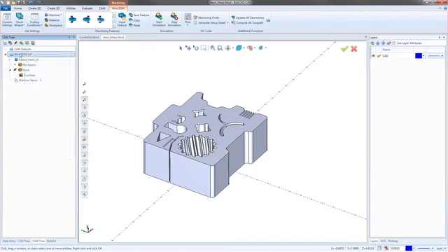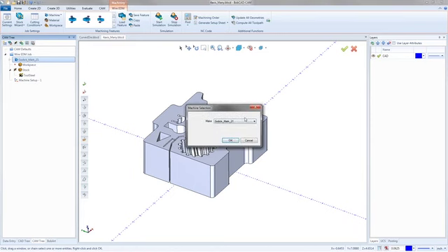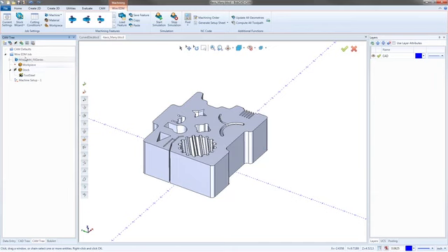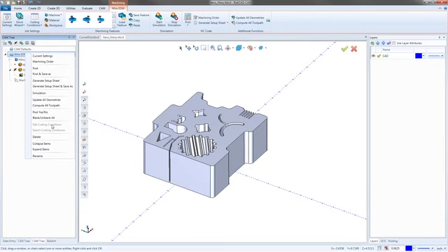Now, if you right click on the Wire EDM job and you do not have that option, so I believe we'll lose that if I choose the Mitsubishi here. You'll see there is no edit cutting conditions. And that's because with this machine, we couldn't get the cutting conditions from the manufacturer. Some of the companies we just couldn't get them from. Mitsubishi looks to be one of those. And the other thing is we don't have anything for the database, so there's no database connected to this.